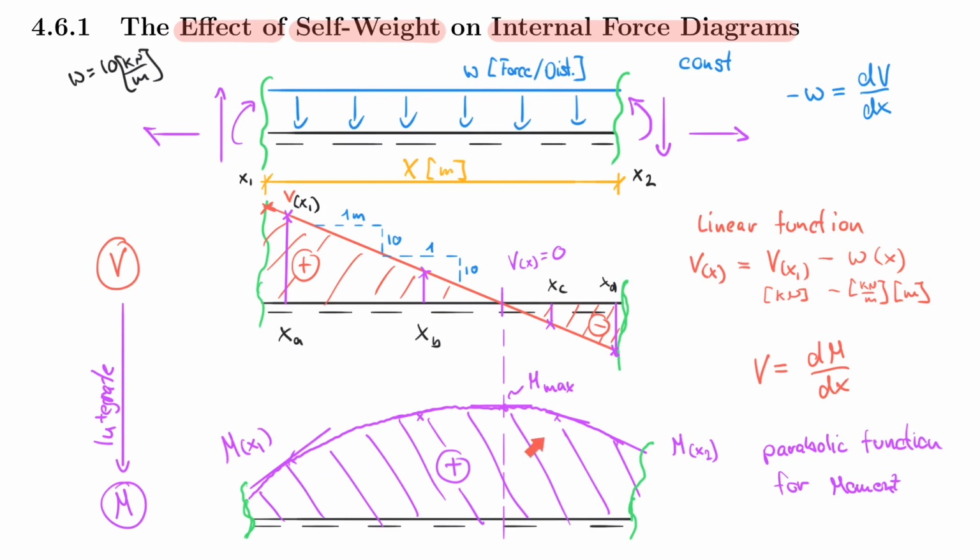In fact, we will actually apply this today. We will not calculate the values everywhere along the line, and we will not set up functions really. That is our goal in our next lecture. But to really understand how these diagrams come about, we really needed to talk about the relation here between the distributed force and the shear force, and the shear force and the moment, all for effectively self-weight or evenly distributed forces.